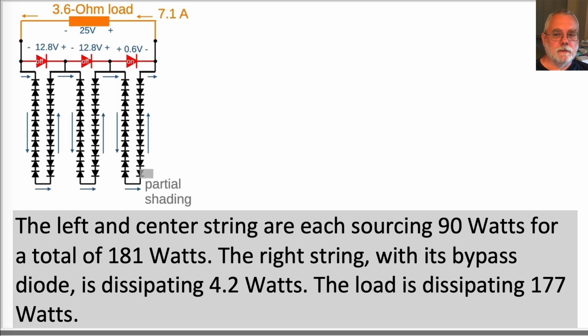The left and center string are each sourcing 90 watts for a total of 181 watts. The right string with its bypass diode is dissipating 4.2 watts.